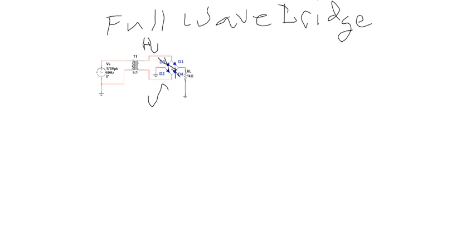That's going to give me an equivalent circuit that looks like this. Again, I've got a complete circuit there because the grounds connect to each other. So that is a completed circuit, and that's going to give me a positive pulse going to the top of the resistor. This is during the positive half cycle.